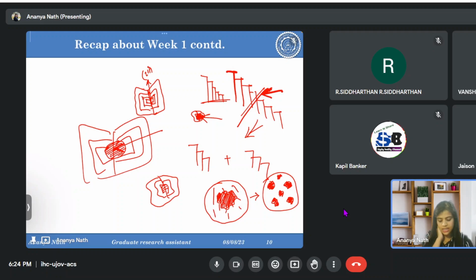So as a result, if we melt the aluminum metal and both the aluminum and silicon are melted, aluminum will solidify faster because of its properties like high thermal conductivity. If aluminum solidifies faster, then if there was a primary silicon and an aluminum growth, it will solidify faster and trap the silicon present inside it.